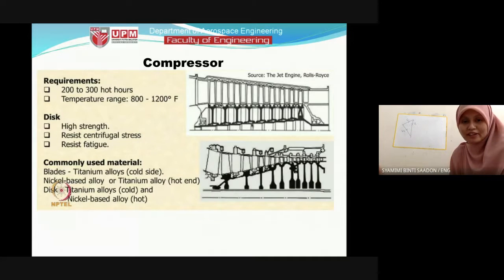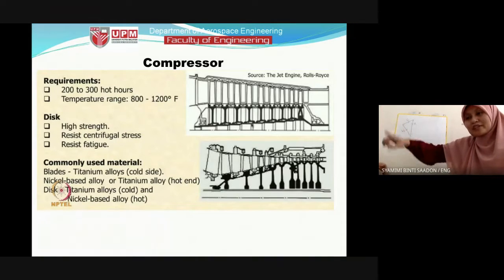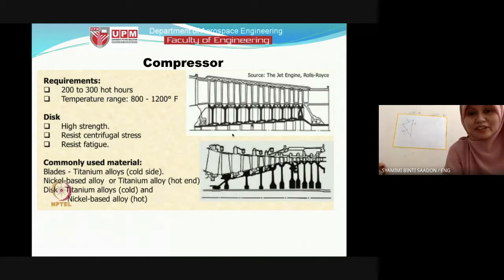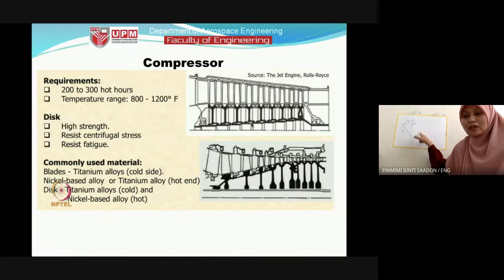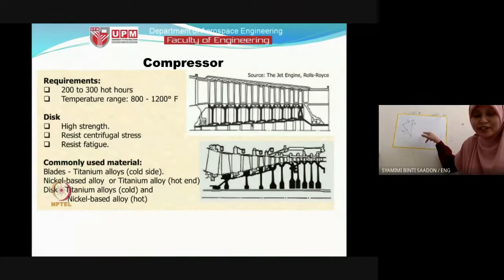So the air enters axially in this direction, and the blade will rotate in this way, axial like this, horizontally, and rotational speed like that, vertically. So that's why the rotational speed for each stage is always in the same direction, it doesn't change for axial compressor. The one that changes is only the relative and absolute velocity, because the blade rotational speed is only in this direction.